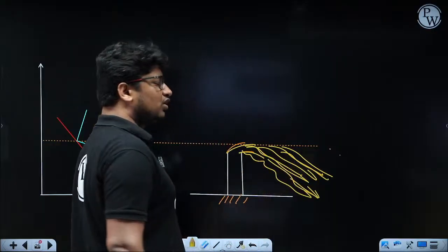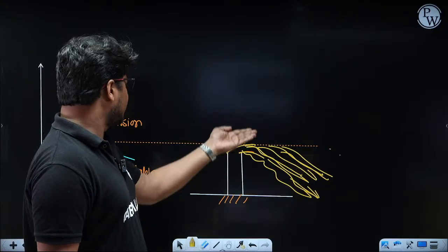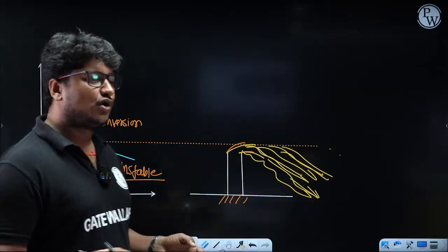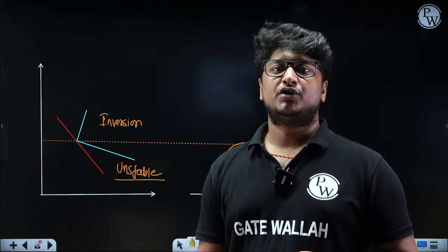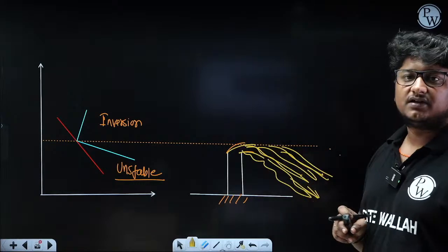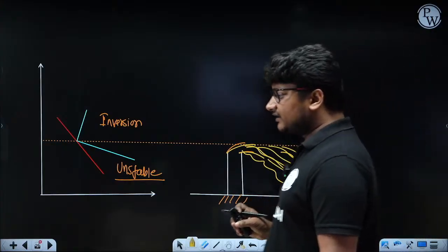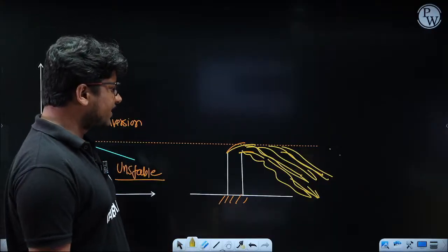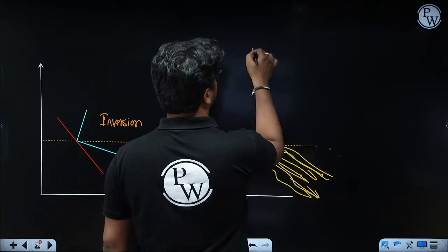No amount of pollutant will go vertically upward because of the inversion layer, which does not allow vertical mixing and does not help in pollutant dispersion and dilution. All the pollutant will go towards the ground, so people living here will be in a fumigated manner. For that reason, we have named this case fumigation.